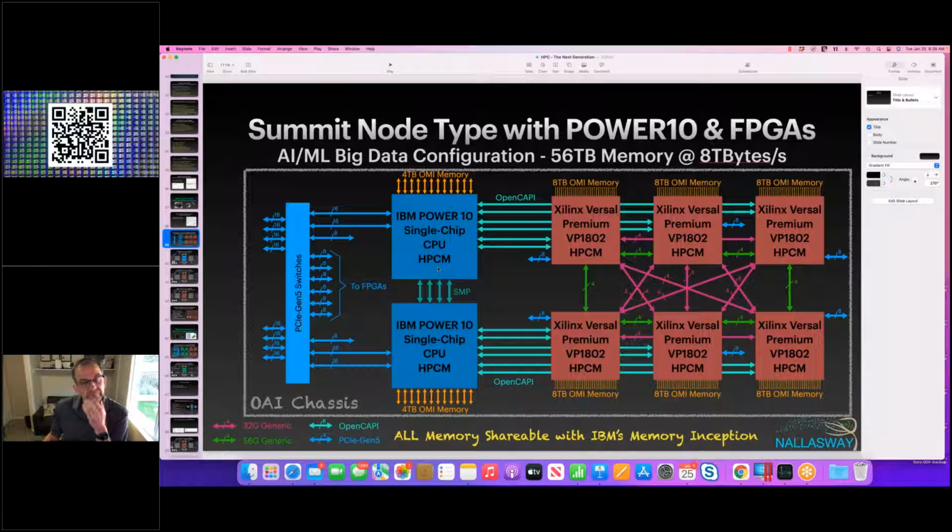Well, if you think about it from the perspective of a standard server, you plug it into the wall, right? So now you've got your BMC up. None of this Power 10, none of this complex would be up and alive, so you wouldn't be able to use that. You would have a BMC that would be alive, talking back to whatever. We have in Power an HMC, or you have some other management box that says, hey, give me your inventory. That goes to the GUI. Hey, power on, power off. So we would need something on standby.